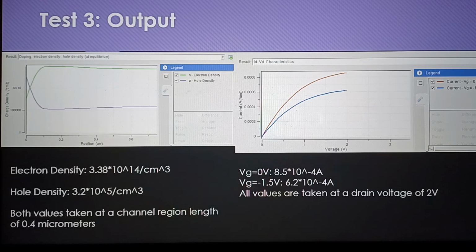So at a given time, it's going back to where the baseline was, where the more gate voltage you put in, the less current can flow through the device at a given time. So that is a result of changing level of doping and downscaling the dimensions of the device in certain aspects.